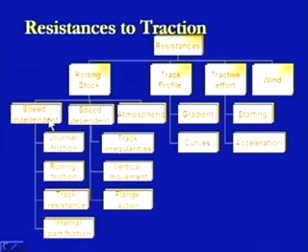Further, there are divisions within the speed independent or the speed dependent resistances, and we will be trying to look at the different resistances. In the case of the speed independent case, that is general friction, rolling friction, track resistance and internal part friction. In the case of the speed dependent, we will be looking at track irregularities, vertical movements of the wheels and the flange action, that is its oscillations with respect to the lateral direction. So, we will be starting with the different types of these resistances.